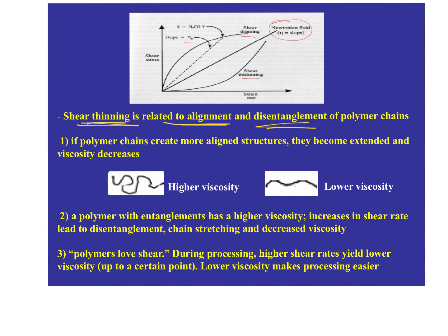If we have polymer chains that are more or less randomly oriented, these are going to give us a lot of viscous entanglements with their neighbors. Going back to that velocity curve, they're all in shear with each other. If they look like this when they're shearing, we're going to have high viscosities because there's entanglement going on with that shearing between the different layers.